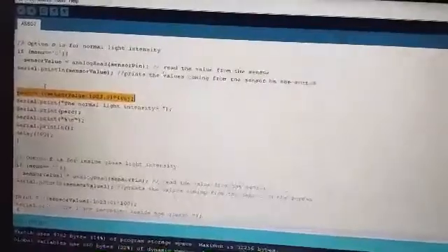Now that is for the temperature. Moving on to percentage, as you can see here, option C, which originally was to read the light intensity when nothing is covering it. This is the formula that I have used. PERC, short for percentage in my program, is equivalent to the sensor value, whatever is detected by the LDR, divided by 1023.0, because once again the LDR also sends a serial count of 0 to 1023, so I used that range and multiplied it by 100 to get the percentage.